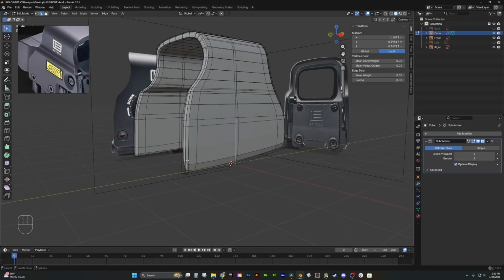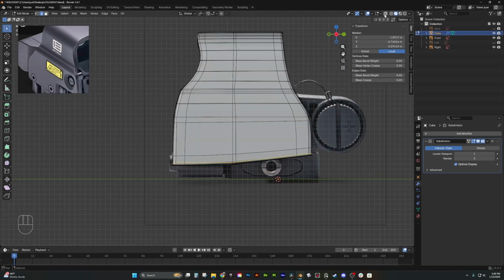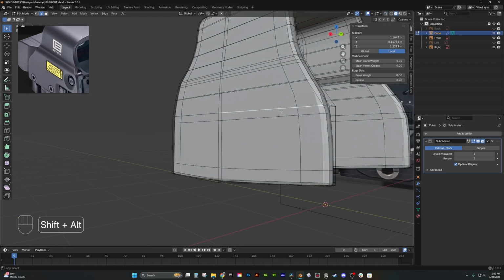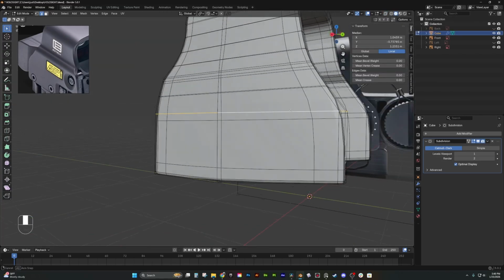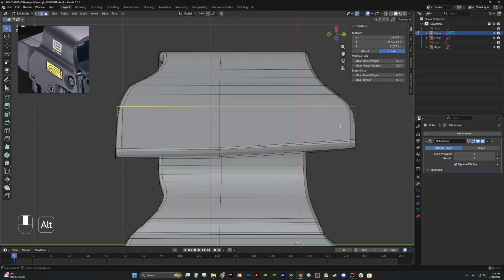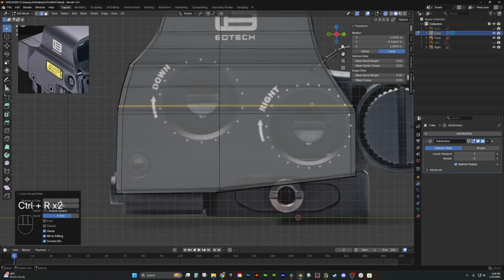So now we lost this bottom edge loop, and I can drag it down and it'll start to sharpen itself out. I'll see how sharp it gets at this corner over here. And go back and forth between X-ray mode. It seems like we only have one edge here, and I'm going to turn wireframe back off. And now we can even sharpen this side a little bit too.